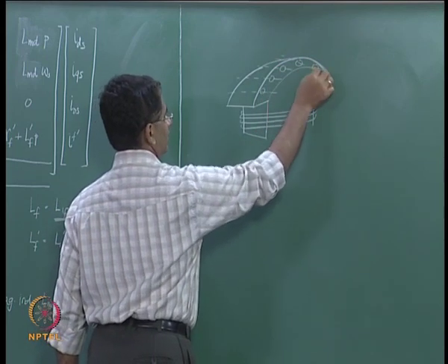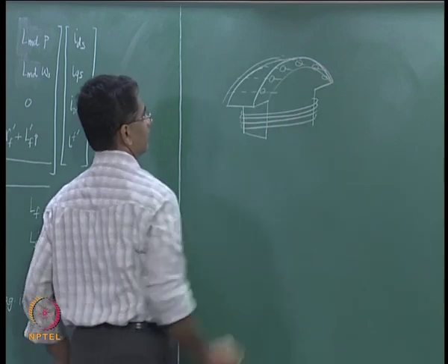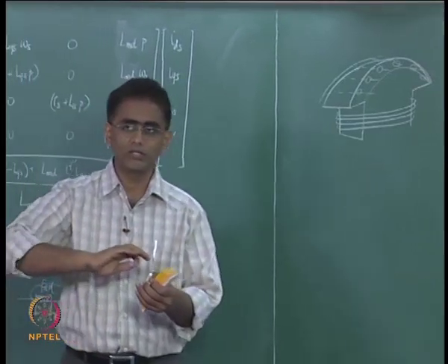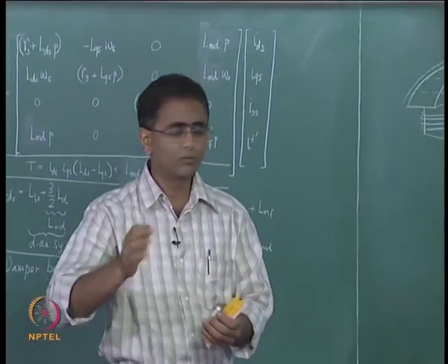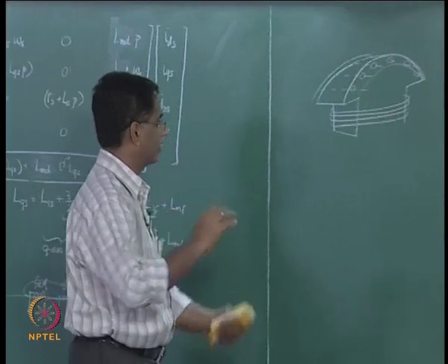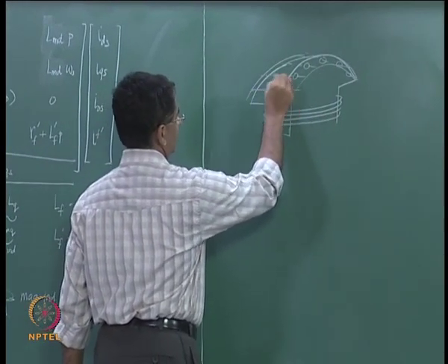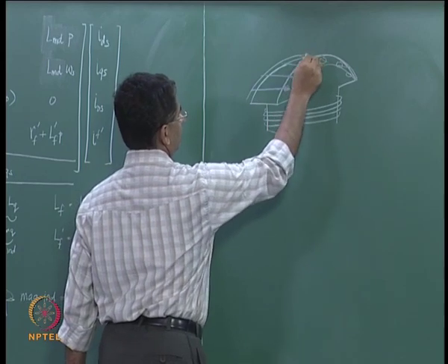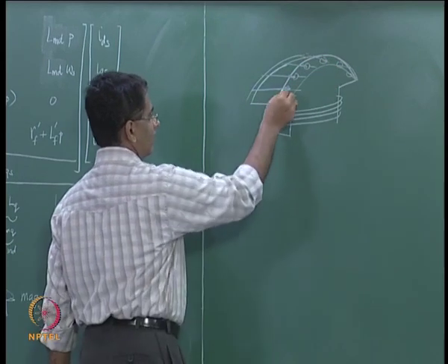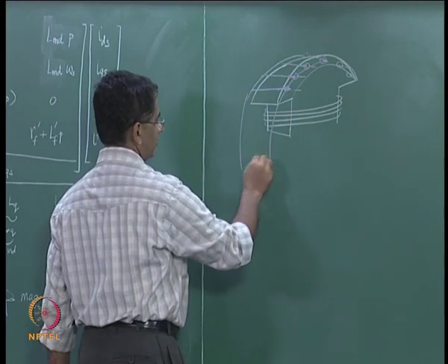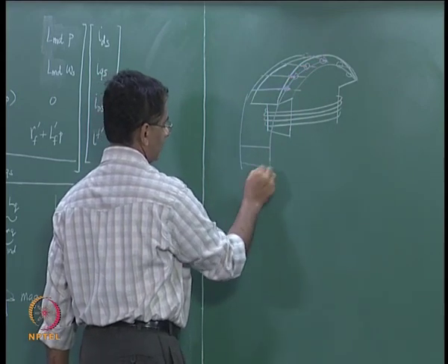and these bars are all shorted here, shorted on this side, with the result that if there is going to be any change in the speed from synchronous speed, either more or less, then there will be induced EMF in these bars and there can be currents that flow in these bars, and the shorting ring connects it to the bars on the next pole face.